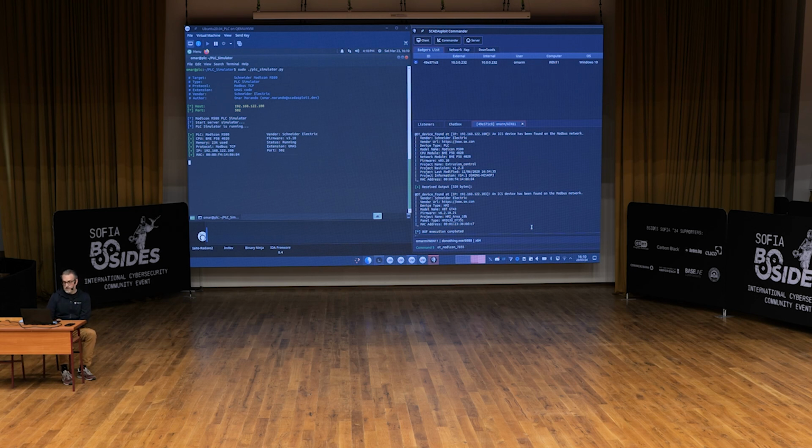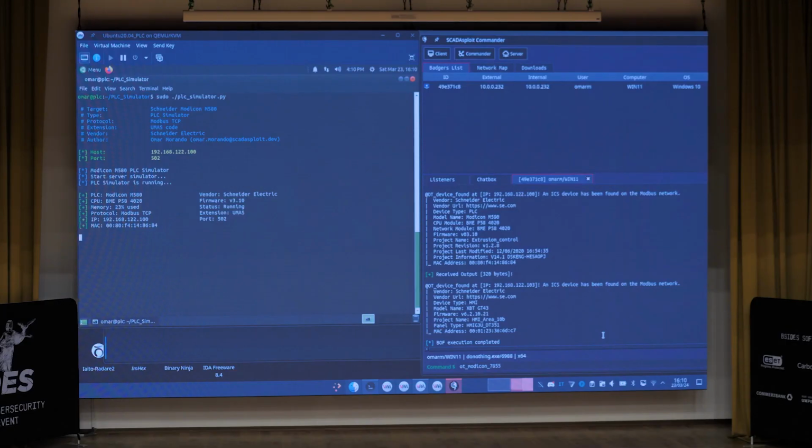But there is a vulnerability inside this PLC. If you set the breakpoint address to 00, you stop the PLC completely. It stops completely. The CPU is stopped, Ethernet communication is stopped. We can try to do that. And the address is this one. Sorry, there is a mistake here.